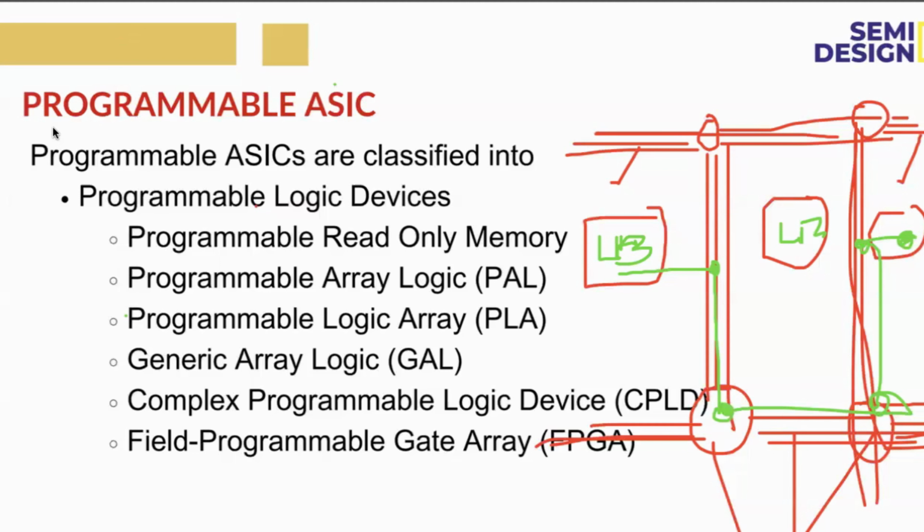So logic blocks are nothing but they implement the sub-functions as we discussed. Those logic functions may be both combinational logic circuits or sequential logic circuits. It will implement both, right? Mainly in the logic block, it consists of the lookup table, as he said. It consists of one lookup table, one register, or we can also say a flip-flop, and the multiplexer. So these are the main three blocks.